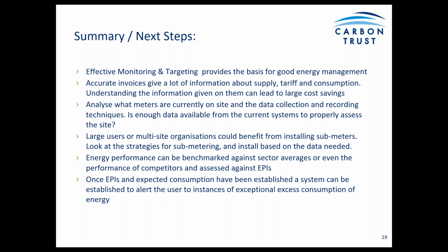So large users or multi-site organizations, for example, may benefit from installing sub-metering of different areas or different processes that are at the site. So you could look at different strategies for sub-metering and then install sub-metering based on the requirements of the site in terms of what data you actually need to see.